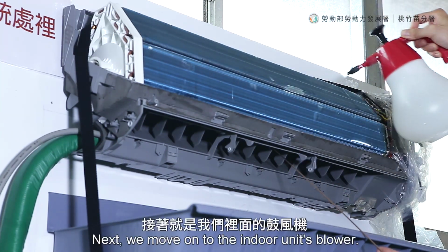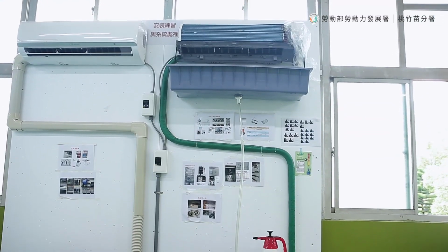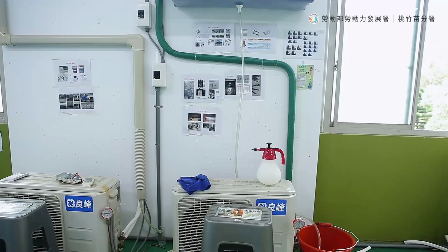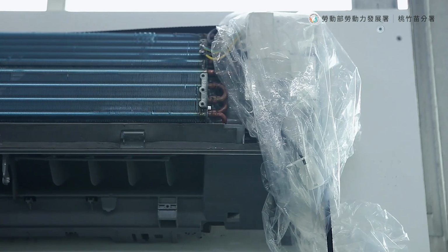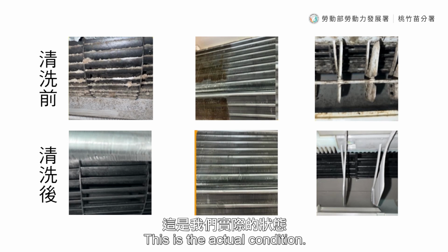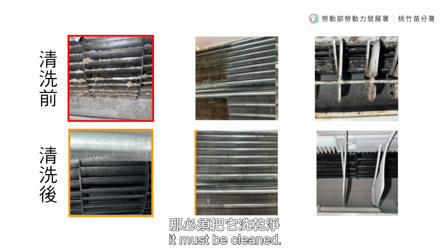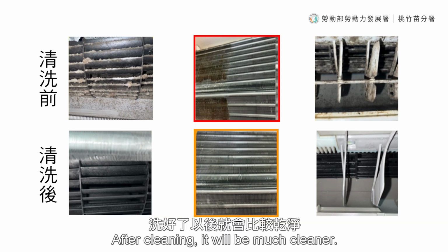Now we move on to the indoor unit's blower, which also requires maintenance. This is the actual condition. This is the blower. Since there's a lot of dust on it, it must be cleaned. This is a heat exchanger, and it's quite dirty. After cleaning, it will be much cleaner.